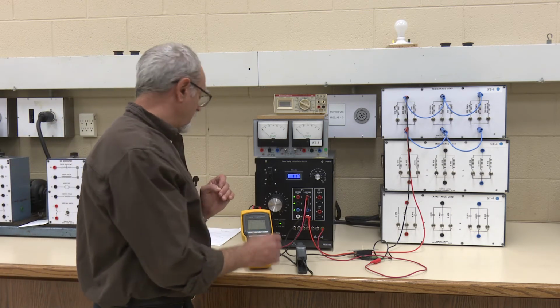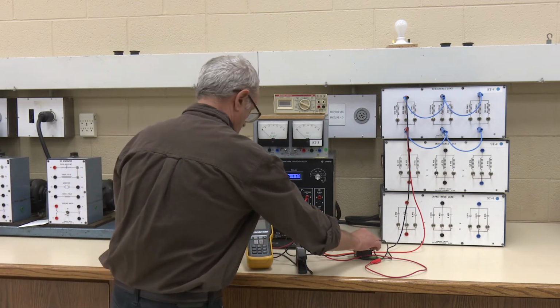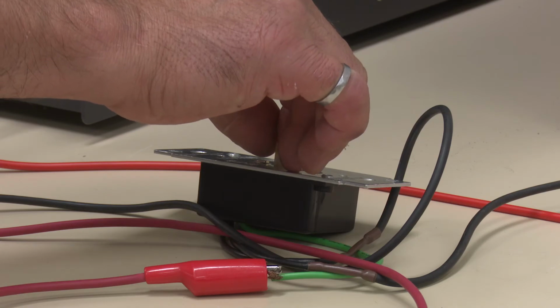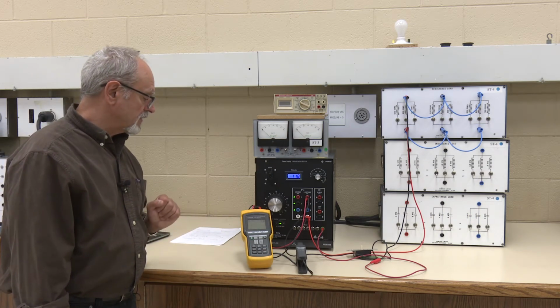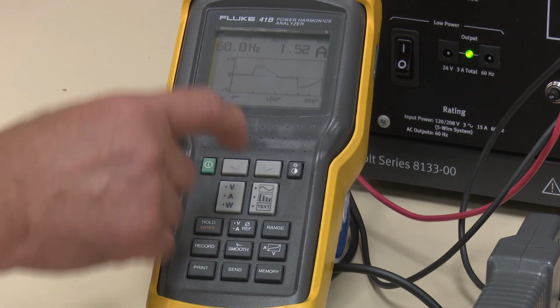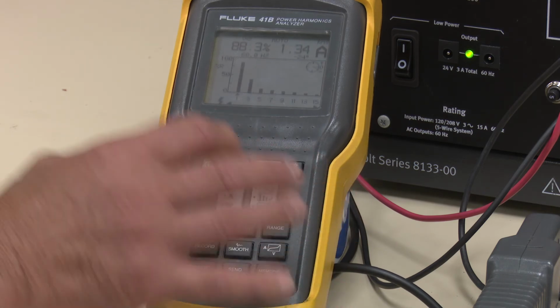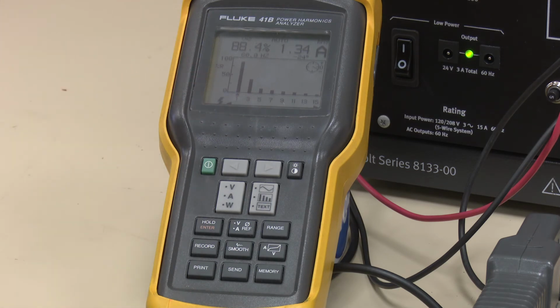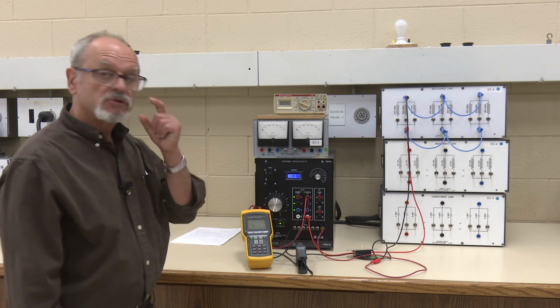Now what we're going to do is drop the effective current to 1.5 amps by adjusting the angle on the TRIAC. And there we go. So the waveform you can see is severely distorted. And now let's have a look at the harmonic content. So we'll toggle to the histogram. And you can see here that if we just adjust over to look at the percentage contribution of the third harmonic, the 180 degree harmonic, we'll see that it's about 40%, 41%, close to what we had surmised earlier.